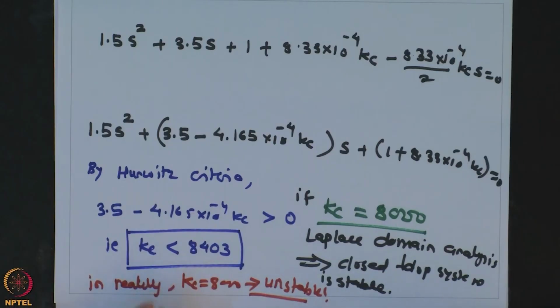Especially for that reason, we need a method which would not require such an approximation of dead time, and that will be possible if we do the stability analysis in the frequency domain. So we will take a break here, and when we come back we will see how the stability analysis for systems with dead time can be accurately handled if we do the analysis in the frequency domain, which is inverse time domain, as against the Laplace domain, which is a complex time domain.